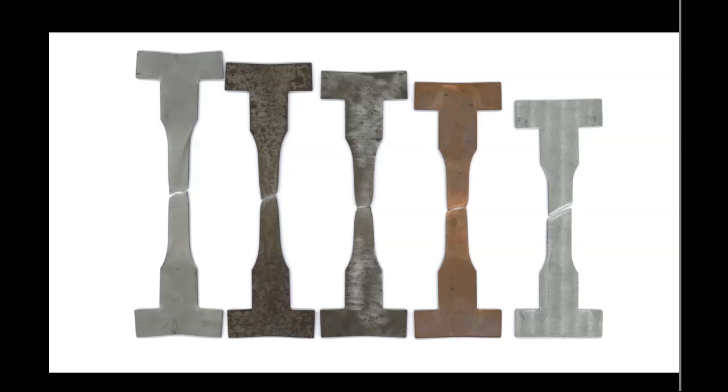Okay, and what you would see is that more ductile materials will have both larger percentage EL, or larger longitudinal elongation value in magnitude, but also larger magnitude in percentage of reduction of cross-sectional area.